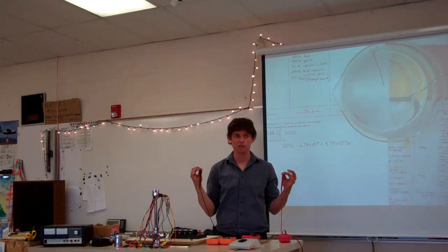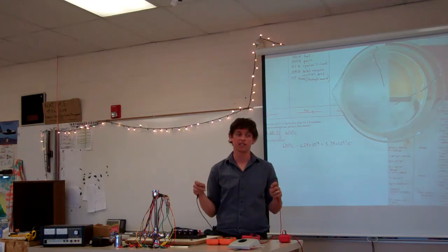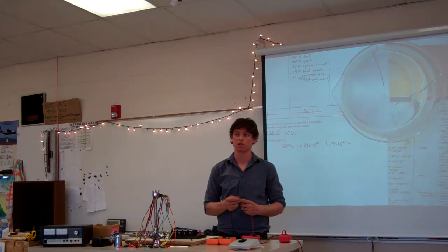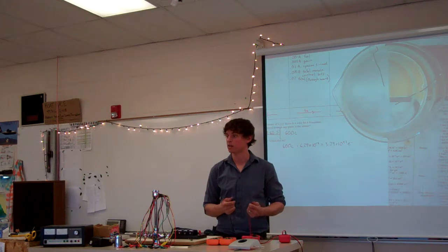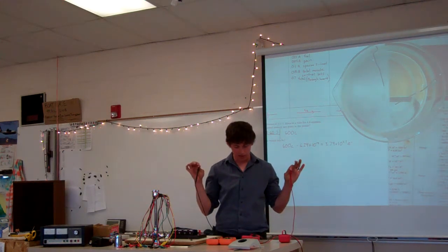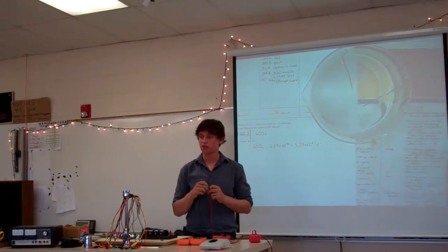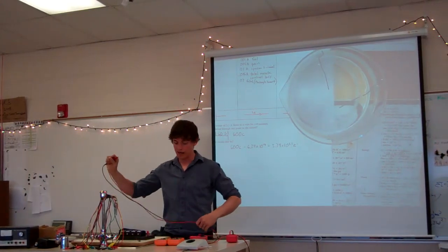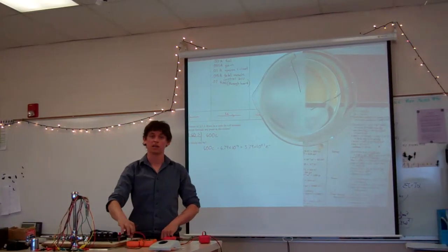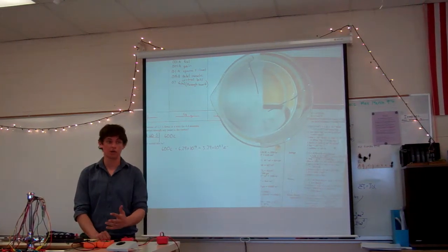Now what if I just got out of the ocean, I've been swimming? Would it go up or down? Down, to about 100 ohms is what I hear. I have not tested that, but I read that in a textbook. Okay, 700,000. So electrical shock happens most commonly in bathrooms because the resistance of the person is way lower, because they just got out of the shower, something like that.